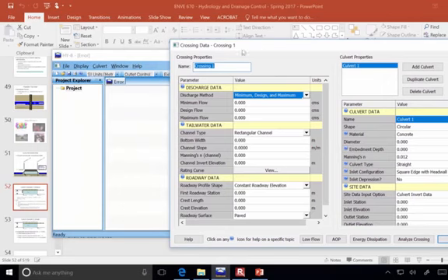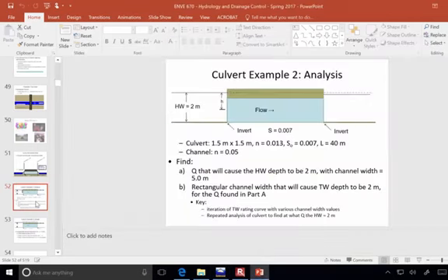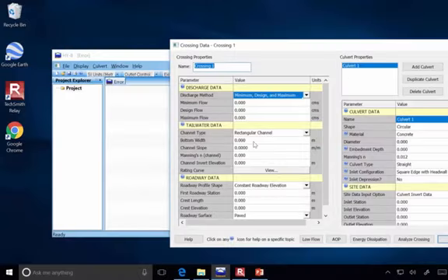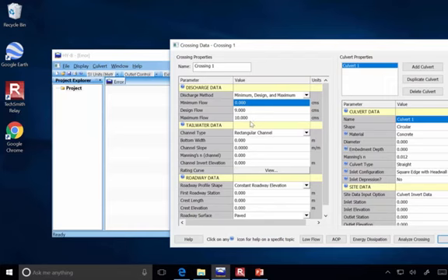All right, so what flow rate do we want to even do for our range here? We don't know the flow rates. This is going to be something we have to play around with a little bit. So I'm just going to start from 0 flow to 10, and for the design flow, I'll have 9. And we may have to go back and change these flow rates to make sure that the calculations are being done within the range that we're interested in.